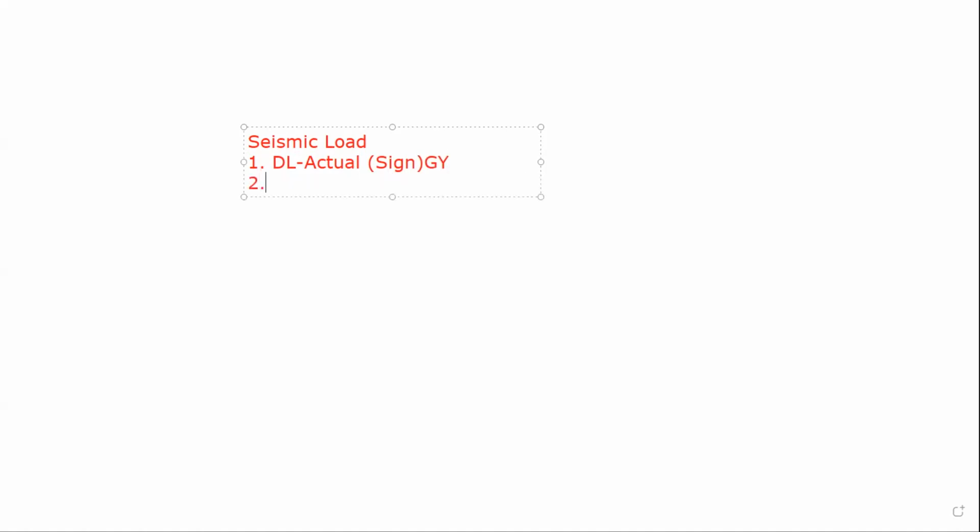And the second thing which we need is the load consideration of the slab. Since we already have defined the slab element and the self weight, it will take self weight automatically. So we don't need to define the slab load, because in some builds you'll find they are taking the slab as, suppose, the slab height is 0.15 meter, and then it will be 25 into 0.15, which means 3.75 kilonewton per meter square they are taking. But here I have defined the slab item, so no need to take that. The self weight it will consider automatically. So I hope you're clear with that.